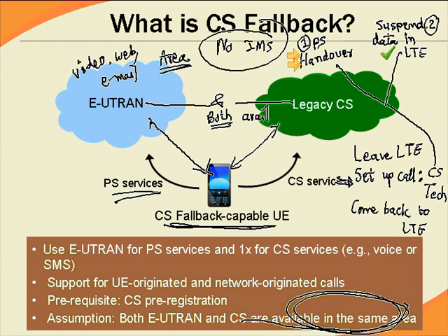Can you have one RF block, where when we are on voice it is 850 and on data it is 700? Is this a cheap handset solution? But again, whenever you have two carrier frequencies, you need two frequency oscillators. You need two separate RF processing blocks.